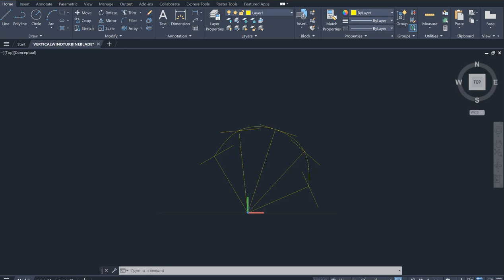And in the previous phases, we just generated the vertical lines. We have the lines of 1 inch off the 6 inch long vertical line in this X direction, and then we just simply rotated each one of those lines by 24 degrees increments: 24, 48, 72, and so on. And then we just simply used a spline command to create an extrusion path joining the far end of the lines.